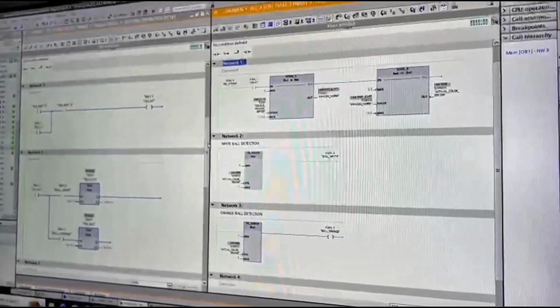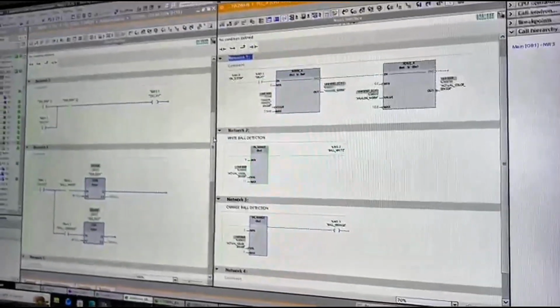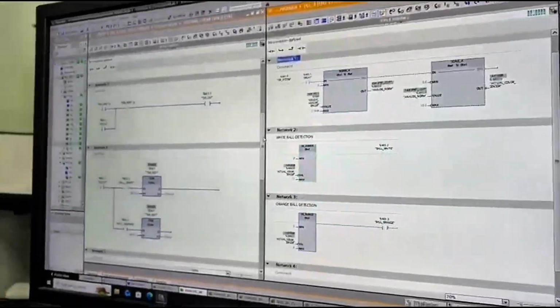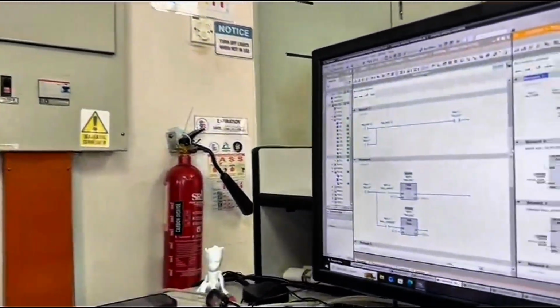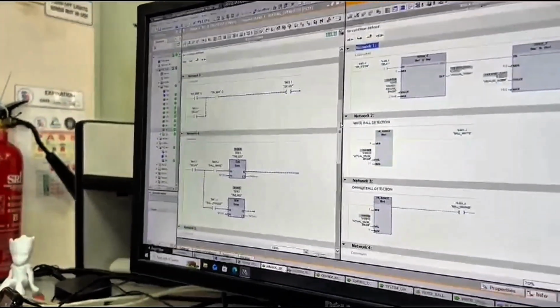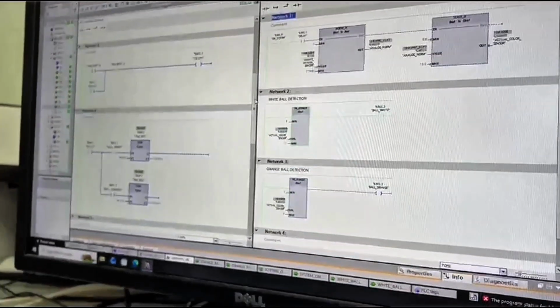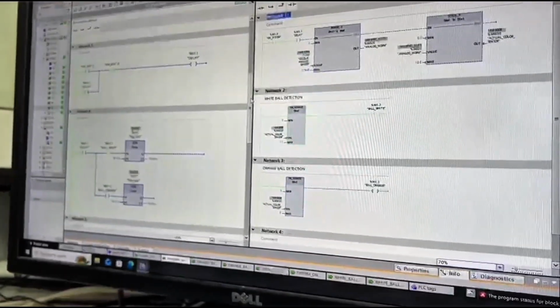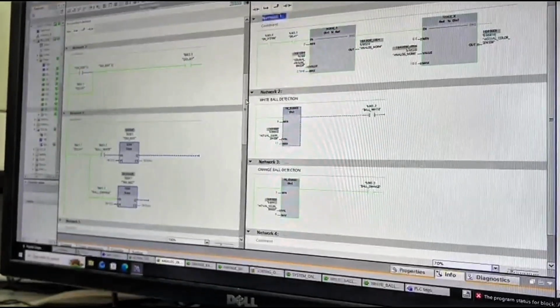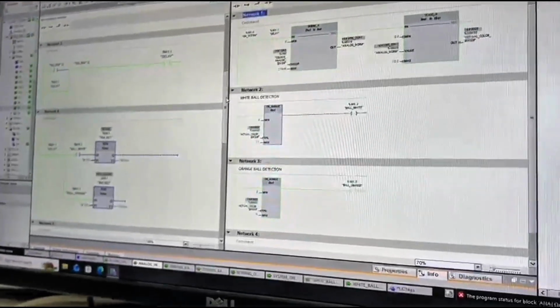If the slider is moved further, it will open contact M3.4, which represents the orange ball, and this will activate timer T002. In network 5, once timer T001 is activated, it will open contact T001 and turn on the bottom cylinder, which functions as the color sensor. In network 6, after the bottom cylinder contact is open, timer T004 will also be activated. Finally, in network 7, when contact T002 is open, it will activate the pusher.